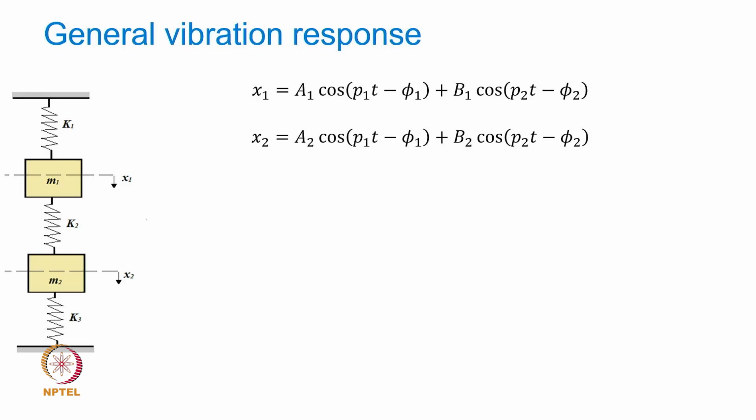Okay. So, therefore, what we wrote is that the amplitude ratio A2 over A1 is given by the first mode shape ratio, right. And if you remember in the previous simpler example, this xr1 was basically equal to 1, or I may write this as plus 1, and xr2, which is the second mode shape, was minus 1, as a specific case where k1 and k3 are k, k2 is 2k, and m1 is equal to m2 is equal to m. Of course, these ratios